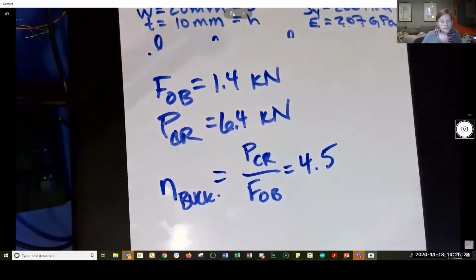Is there a general range for factor of safety that's used, or do you just determine it based on the situation? It's very much contextual. And as we start talking about failure theory, we'll see how the different failure theories also give us a different understanding of what that factor of safety might be. If things are stationary, factor of safety is not necessarily as important. You might be wasting material, but you're not trying to move something.